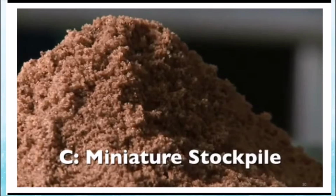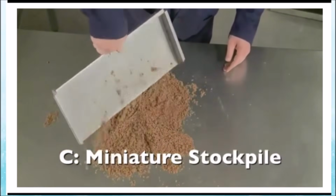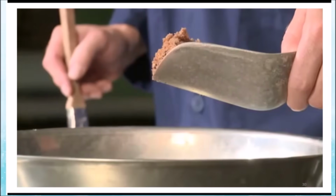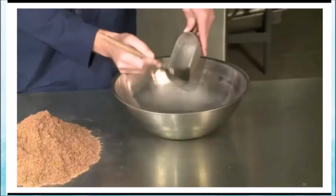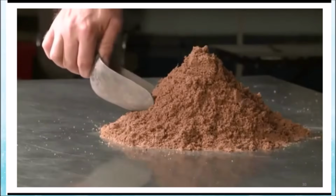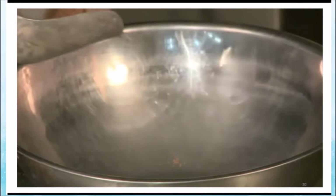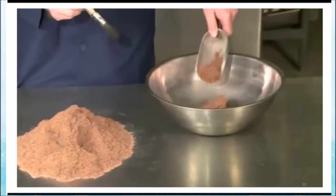Used for damp fine aggregates only, Method C is procedurally identical to Method B, except that the conical pile is not required to be flattened, and a small sample thief or a small scoop or spoon is used to obtain the desired sample. From the resulting miniature stockpile, obtain a sample for each test by taking a minimum of 5 increments from randomly selected locations.